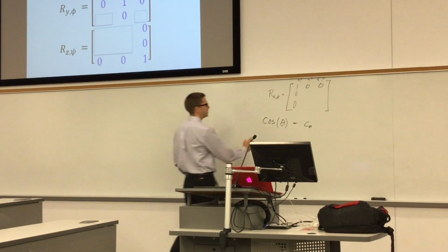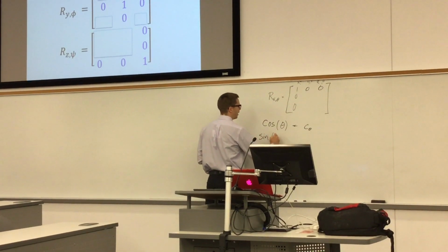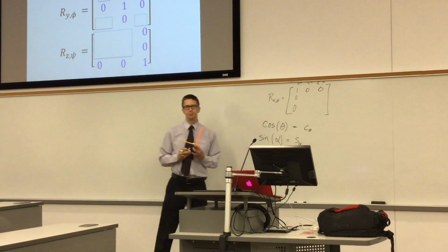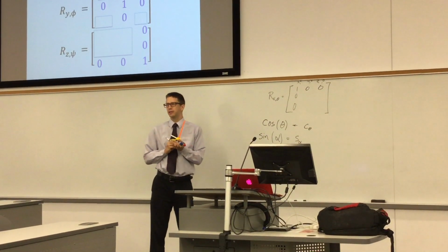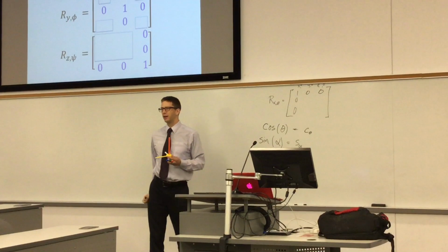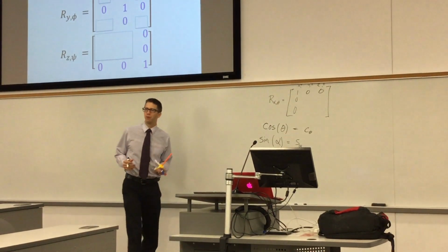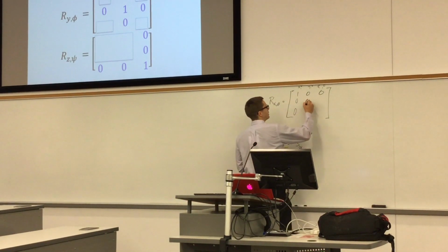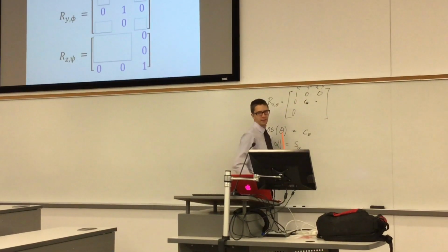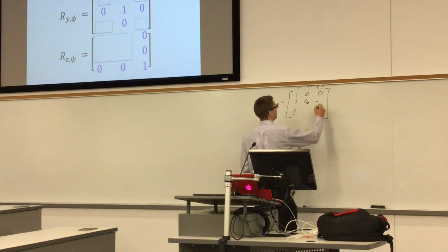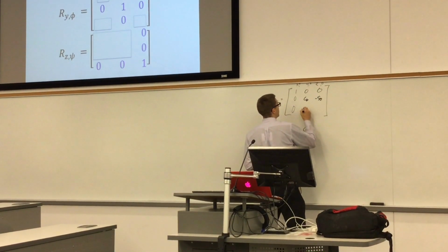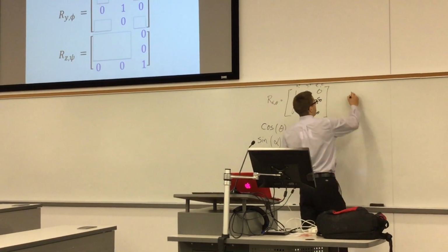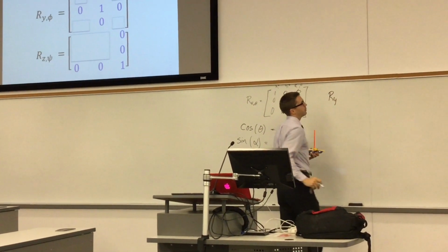Similarly, for sine of alpha, we'd write S subscript alpha. Because if we don't start doing this, once we put a couple joints in here, we're going to have an alphabet soup and it won't fit on one page. So this is the simplification we're going to do. And so we get C theta, minus S theta, S theta, C theta.